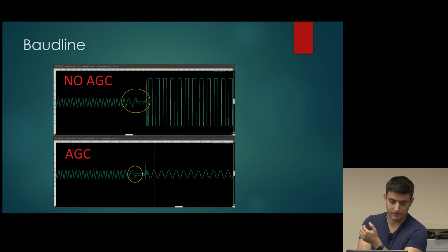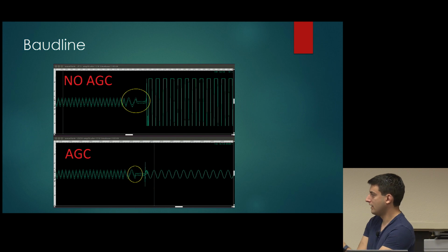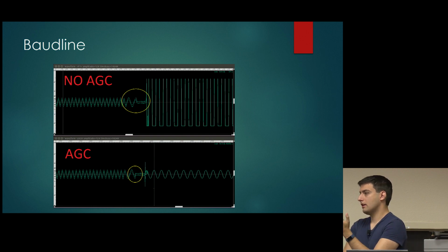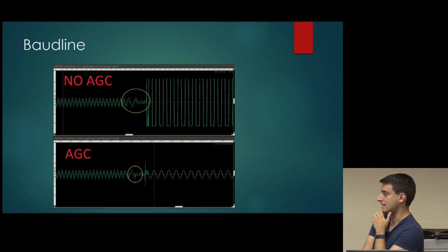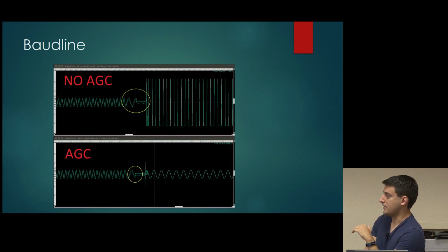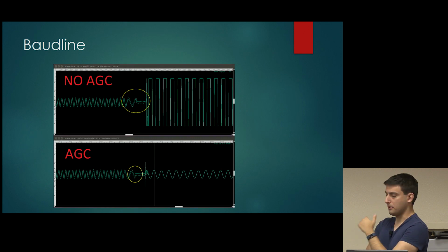So you go from a nice sine wave over to a clipped sine wave. The lull in the middle is an artifact of the VSG, because the VSG has some internal relays that it needs to flip in order to get the appropriate gain setting out. So that flat line in the middle has nothing to do with the receiver and has everything to do with the VSG.